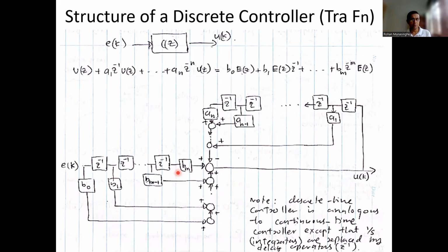And when the time ticks by 1 step, you discard the oldest error, maybe at 5 seconds, you drop it and shift all these errors backwards, leaving the space for the new error which is coming up. Likewise, at all times you maintain the present error and the recent number of error samples, depending on how many are required based on your dynamics.